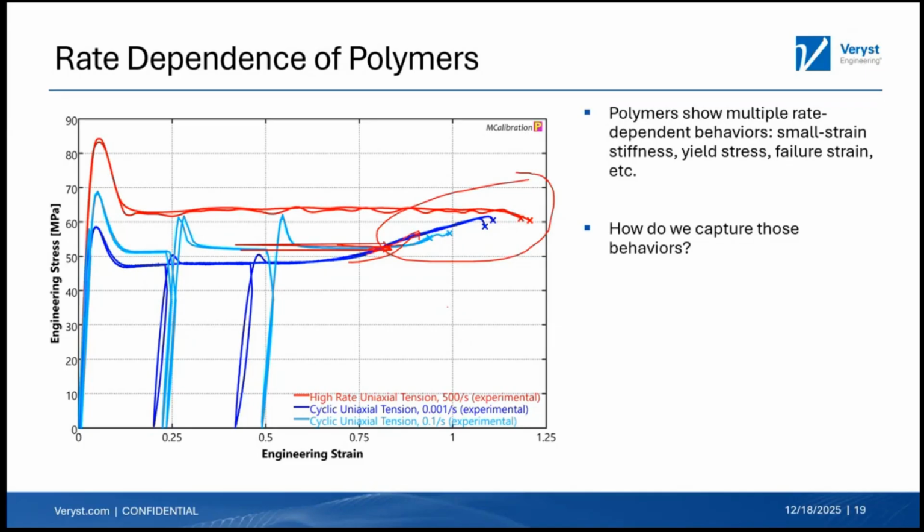The caveats to that are if we want to get failure data and you want some statistical data, we need more, and part of that's going to depend on what type of material. Is it ductile failure? Is it brittle? The other thing that we might want to talk about is the temperature that you're at. If you're near the glass transition temperature and you're doing some testing, I generally ask for more, because temperature and rate dependence are highly correlated and intertangled in polymers, and you'll see more variability. So we'd want to nail that down a little bit more.